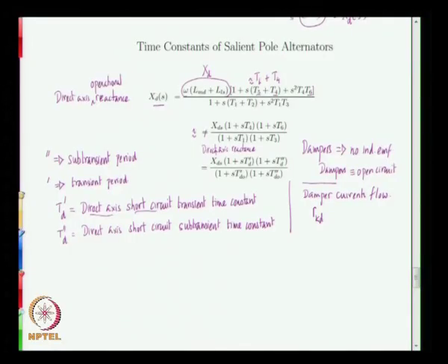However, because the resistance of the damper circuit is pretty high, these induced EMFs cause some currents to flow, and this induced behavior will decay down pretty fast. Because R_KD is high, the damper currents die down fairly fast.